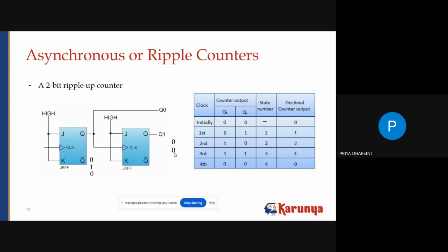So we go to the third clock pulse. When you apply the third clock pulse, you are giving a negative clock pulse directly, so this JK flip flop will undergo a toggle. From 1, it shifts to 0. Now the first flip flop output is undergoing a toggle from 1 to 0, so the negative edge is activated. When it is activated, the second flip flop will be toggled, so from 0 it will shift to 1. Similarly, you apply the fourth clock pulse, and the data here will shift from 0 to 1. Now 0 to 1 is in the rising direction, so it will not trigger the second flip flop. The same data will be repeated.